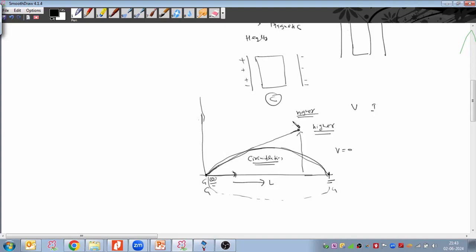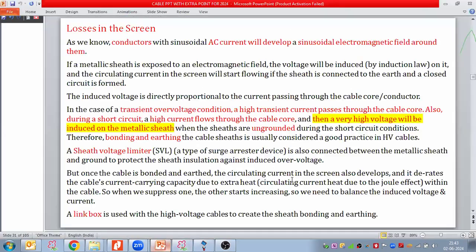This higher voltage will be surrounding the ground, and if any metallic object, any pipeline, any railway line is exposed by chance, at that moment a high current starts flowing in the surroundings. If it is ungrounded, then voltage will be there, current will be zero. Okay. And insulation requirement will also be increased. Yes, so in both cases we have to deal with it.